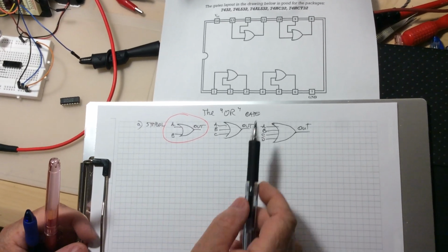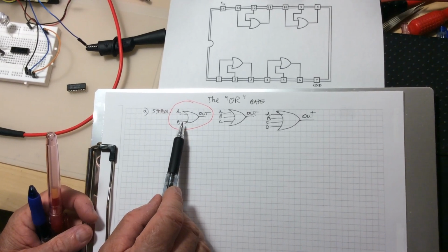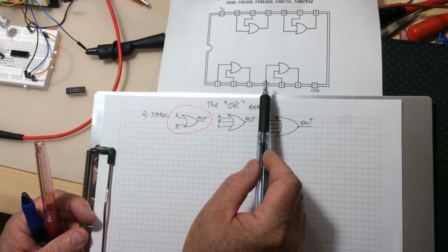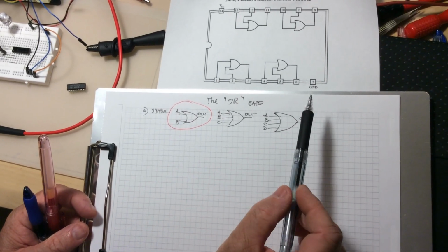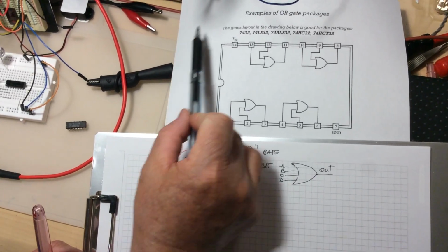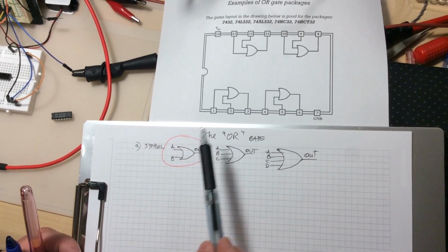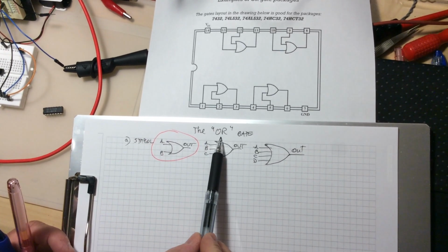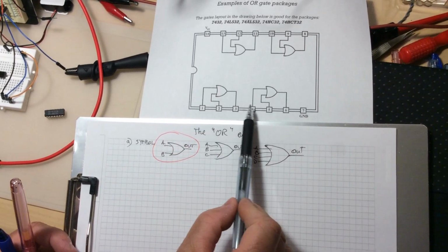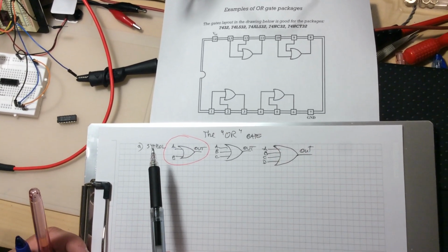But remember, the manufacturers don't make packages only to contain 1 gate inside, because the smallest packages they make have 14 terminals at least. From the 14 terminals, they reserve 1, like this one for the ground, and this one for the power supply, for everything which is inside. So 14 minus 2 is 12. If each of these functions or gates contain 1, 2, 3 terminals, 4 gates are fitting perfectly inside. 1, 2, 3, and 4.